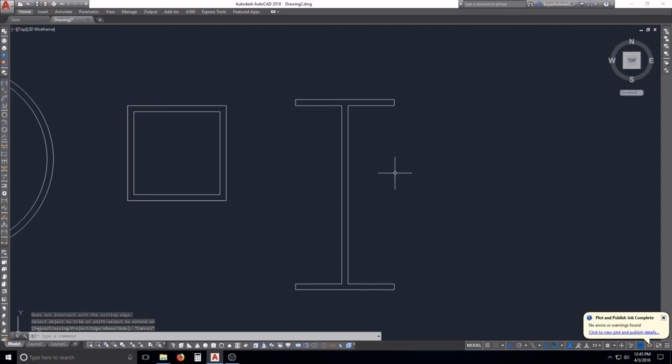All right, so from here, it's not really going to work if you want to extrude these out, because it's really not one solid shape. What we can do is join. Again, I'll even do this one. We'll explode this, and we'll come back and repeat this process again on this one, because now these are all single lines.